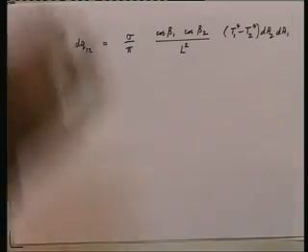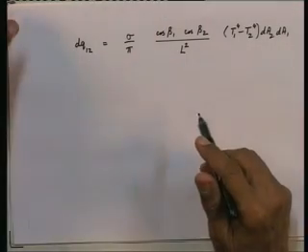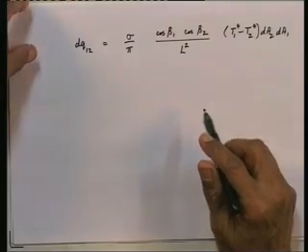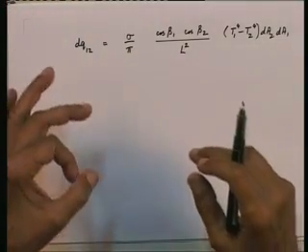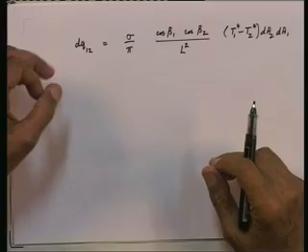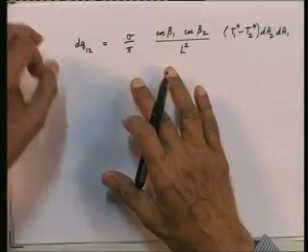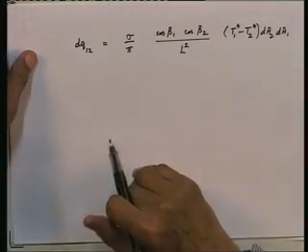Obviously, if we want to know what is the value for two finite size surfaces and we know the expression for two differential areas, it follows that all we have to do is to integrate the expression which we have for differential areas. And we will have to integrate over the area A1 and also over the area A2, which means the expression which I have put down here for dQ1 to 2.